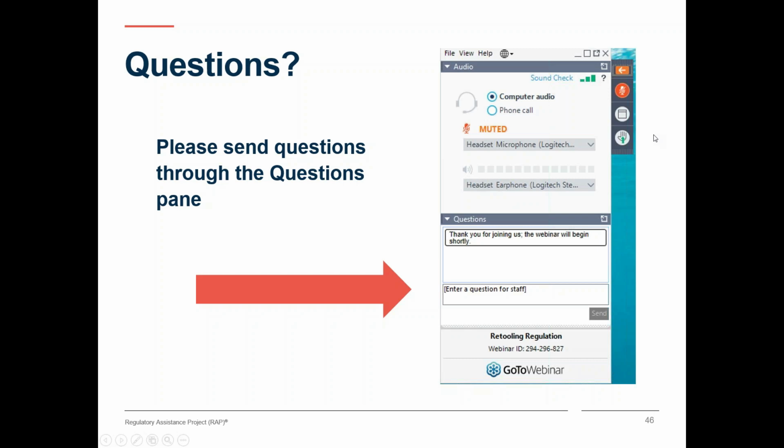City of Burbank, California was an early smart grid pioneer, one of the largest grant receivers per capita in the Recovery Act in 2009. And the system they installed had a fiber optic ring through the service territory for data delivery to the central computer center, and a Wi-Fi mesh to reach from the meters to the fiber optic ring, and then smart meters at the house. When they got the system installed and up and running, they found that they could read all the meters in the entire city in about 9 minutes a month.